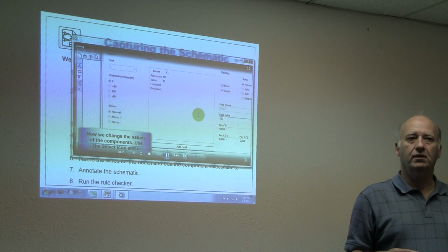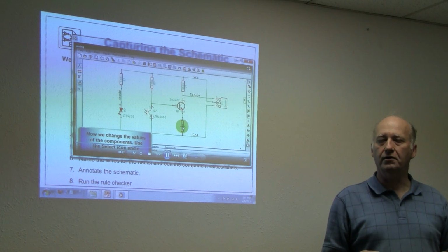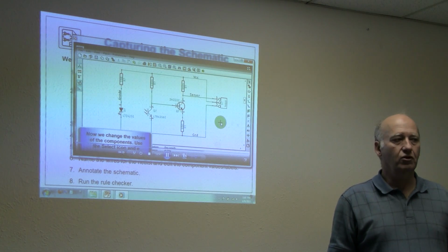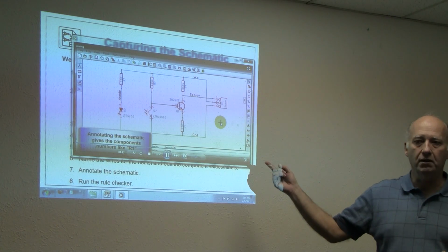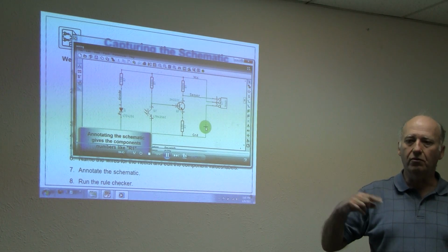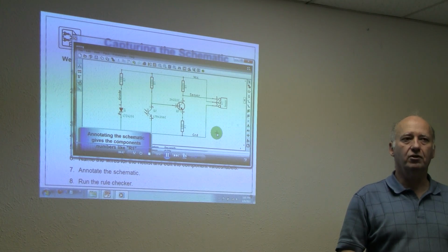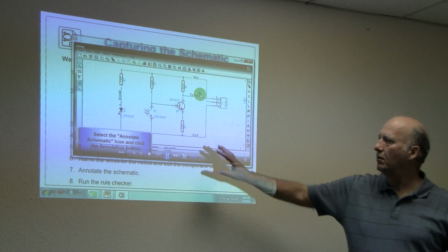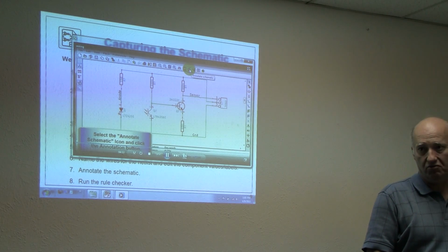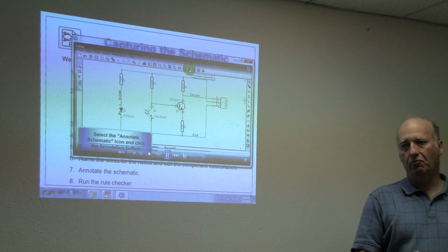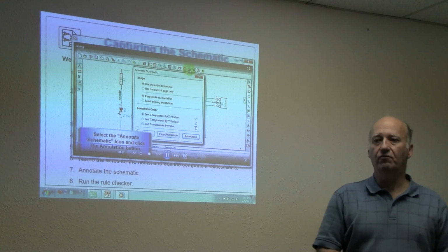And what I really wanted on the silk screen was on-off. So it was better to do it at this point, because you can do it later, but you have to make sure that you not only save this, but you also have to make sure you save the updated Netlist. And it ripples through further the later you do it.